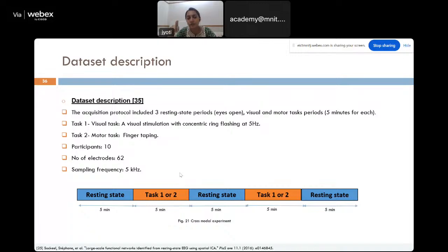If you process data for one subject, there were total, I guess, around 20 or so subjects, I don't remember exactly. For even one subject we have 25 minutes of data, and for each second we have 5,000 samples, so it will take too much time to process. So obviously here I have down sampled my data to 500 only, 10 times, because I was not interested in very high frequencies. To reduce the complexity of my approach, we have down sampled my data here.